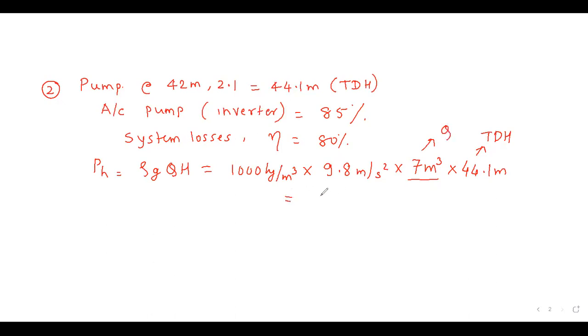That gives you around 840 watt hour. Divided by 3600, and divided by 5 hours, which we have taken, you get the rating of 168 watts. Why this 5 hours? This 5 hours is the average sunshine hours.